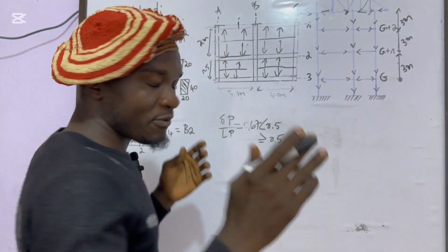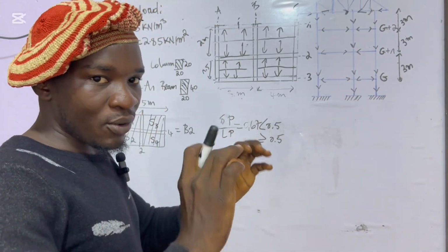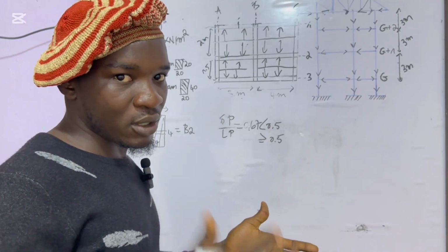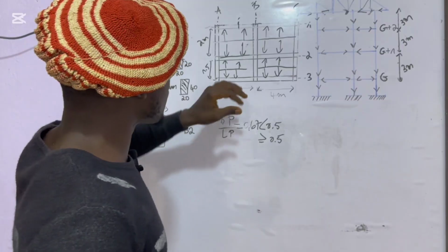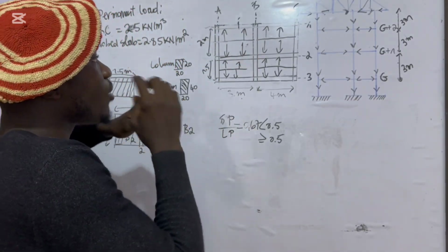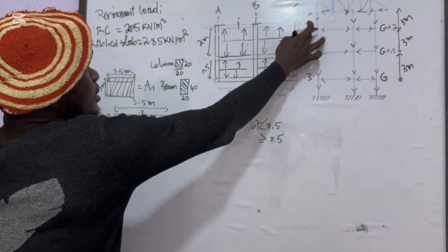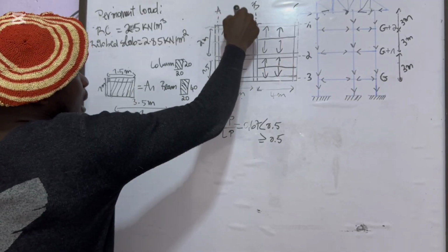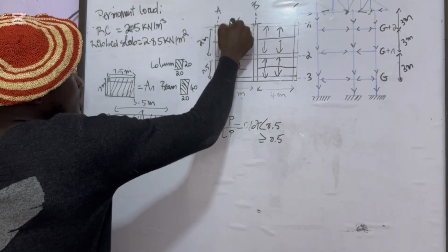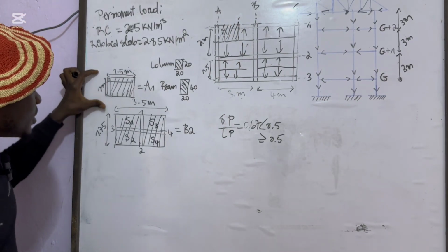I have made a video where I explain how and why the orientation of the column or the beam in a 2D drawing is important. You can check on the channel there. So this is it. Once you have the repartition of load, now you can find the influence area of column A1, at the intersection of axis 1 and axis A. If you cut it, this is the influence area of column A1, which I have represented here.